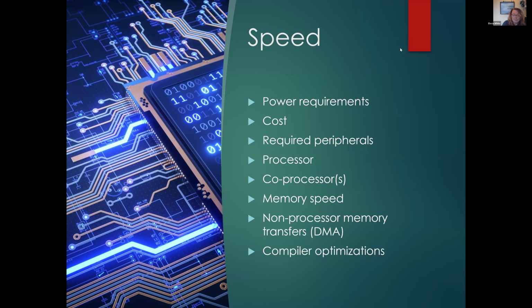Speed also gets limited in different ways. Slower clocks consume less power. That means you'll need to optimize the code to get more done in fewer cycles to make your wearable battery last longer. Or you may have a system that skimps on processing power because slower processors are generally cheaper. Less memory also makes for a cheaper and more power efficient system.